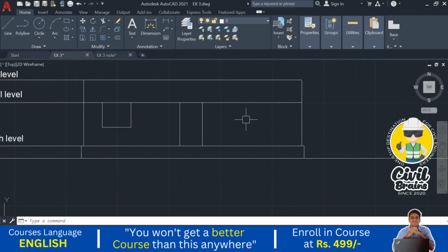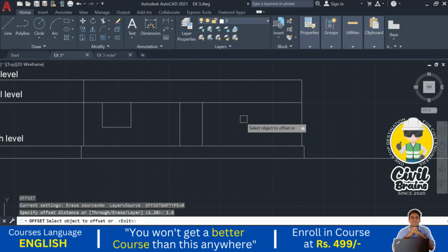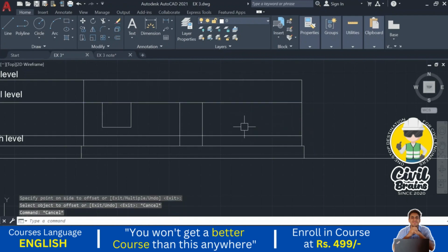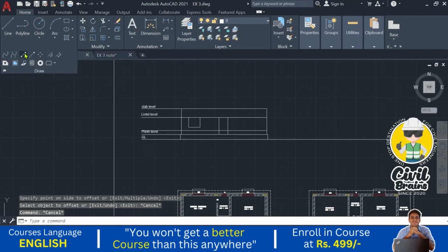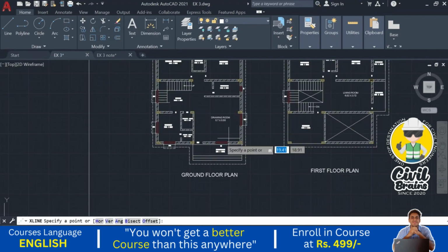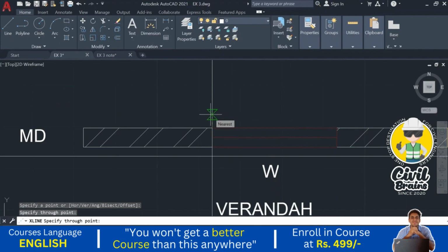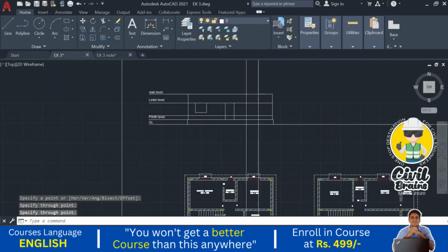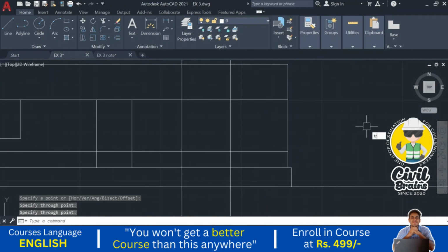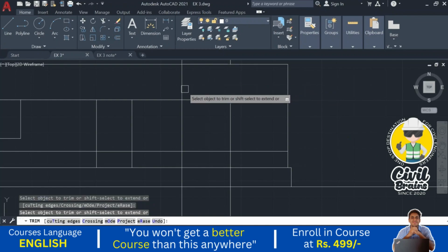I just go to the offset command, press enter. 1.6, press enter. Okay, now I just extend the W. I go here, click on this corner, press enter, and again click on this corner, press enter. So remaining part I just trim.